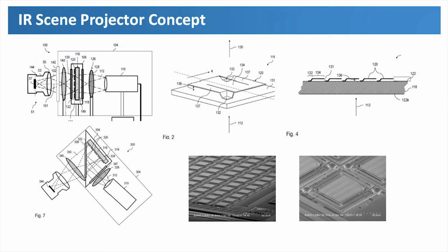The frame rate of the whole setup depends on two factors: on the speed of the chip and the speed of the projector. Actually, in our design, the chip is always faster than the projector being used. So actually, we can think about the operation approaching 600 hertz and maybe even more. This goes back to the response time of the chip. We can produce the chips with the response time down to about 2 milliseconds or even below a millisecond.